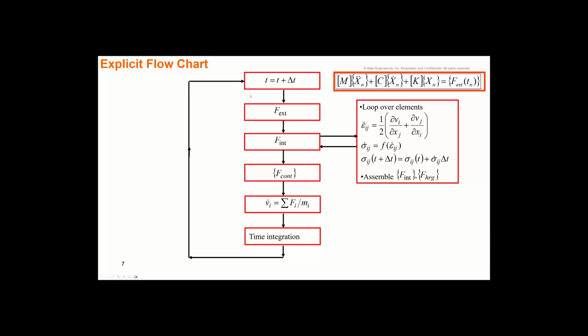We are in the time domain. We are computing the external forces, internal forces coming from the material models and so on, and doing the time integration in the time domain. The loop here is infinite, which means the user has to explicitly define the termination time for this kind of simulation. We do not have any convergence criteria. This goes on in the time domain until the user defines the stop time.